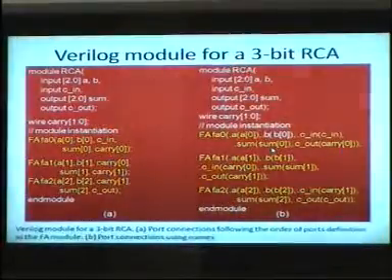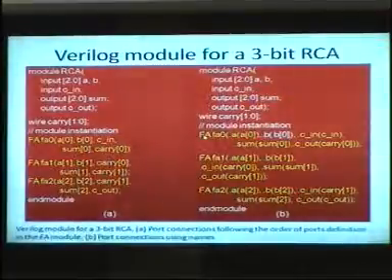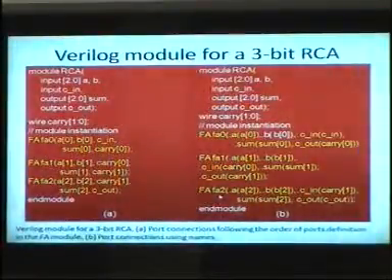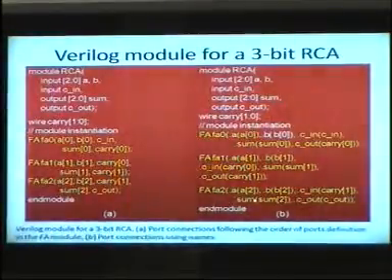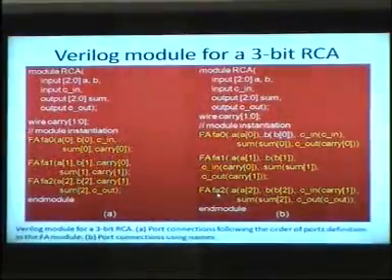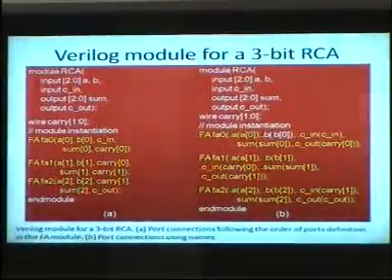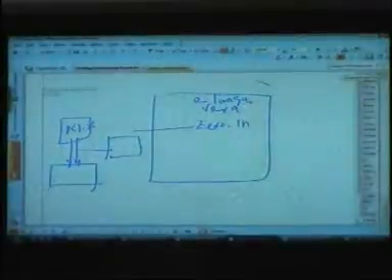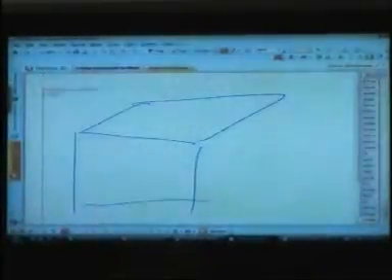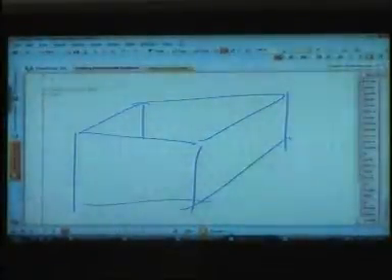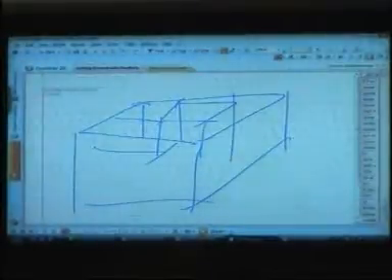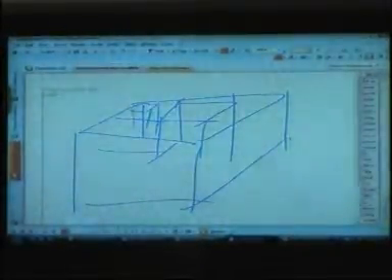So you write a full adder module, its instances full adder 0, full adder 1, and full adder 2. So 3 instances with these names, and this is your whole design. So a bigger box and then smaller boxes. A good design usually is, I always think, and you must always think in terms of a bigger box, which is your top level module. As long as you can keep up with this practice, then you have smaller boxes, and inside smaller boxes you have even smaller boxes.